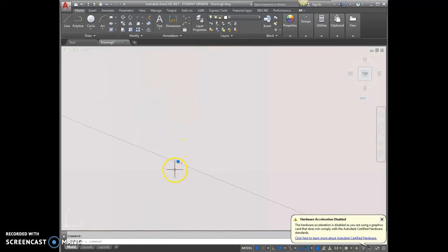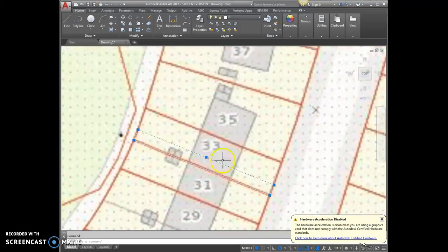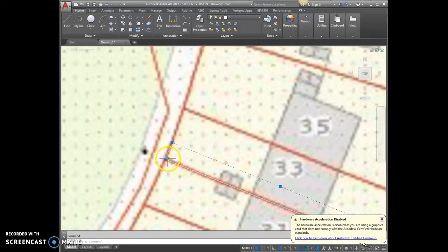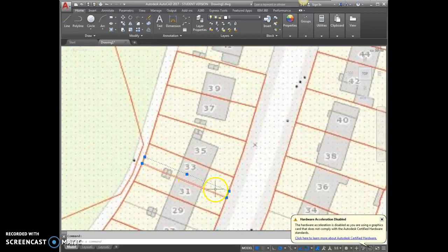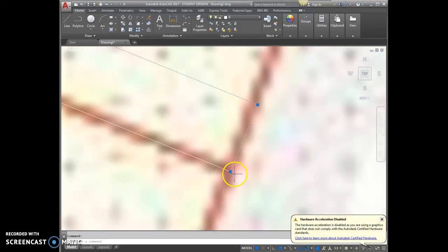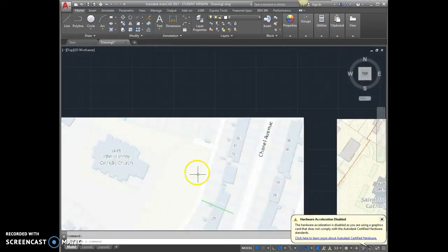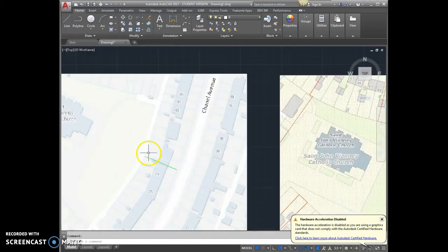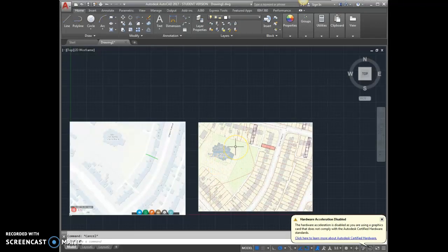And again, we said it should be around 26.5, and it's 26.6. Now, that may be dictated by where we took it here, because we're 100 mil out, so it could be that we went a little bit big on the line, or it could be back here that we went a little bit small on the line. Or else it could be that there's a slight discrepancy between the scales between the two drawings, okay? But again, we're not too far away from each other.